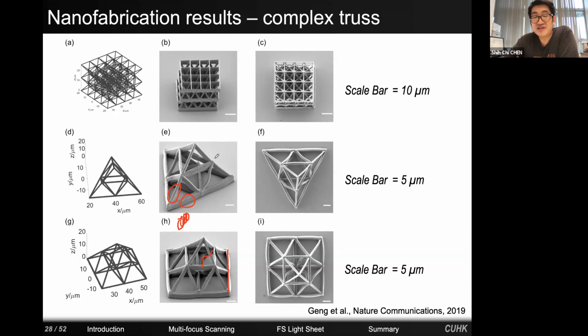Remember, you have a freestanding structure. As you dry the resin or a cleaning solution, the liquid surface tension brings down the structure and sometimes damages it. To resolve the issue, the same solution can be used: a CO2 supercritical drying system or a freeze dryer to remove the liquid through sublimation is a good way.